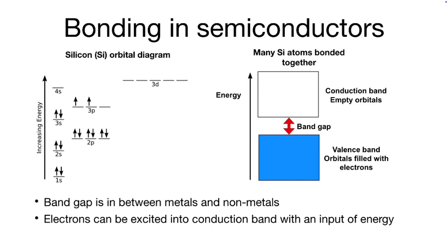Electrons move around. But I get electrons moving around in a wire and I don't get light. Why do LEDs cause it? When we look at an LED, we're putting a load on it. We're pushing electrons into that system. Where are those electrons going to go? They're going to go into our LED, into the conduction band. They can't go into the valence band because the valence band is full.